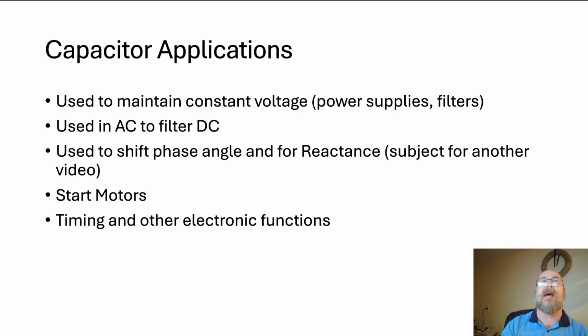And so we do that with a capacitor that is essentially energizing those fields in sequence until the motor is started running. So you'll see capacitors, the little hump on the side of a single phase motor contains a fairly substantial capacitor. That's what's in there to start that motor.